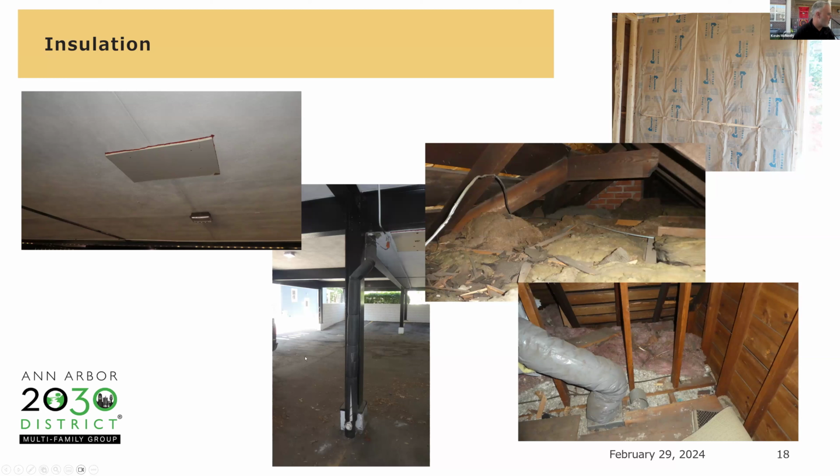If you have a parking area underneath your building, you need to be careful on insulation, so that you do not isolate plumbing that might be in the ceiling assembly above the parking and below the floor of the apartment above. If you isolate it, you're going to have freezing issues. So just make sure that you consult with someone that can talk you through.